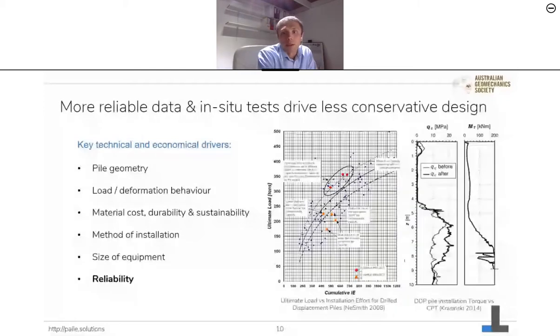Reliability is another factor to be considered, and reliability of constructed piles may vary depending on the chosen method of installation and monitoring. For example, precast-driven piles driven to set under professional supervision and with full monitoring and data analytics will provide much greater level of confidence as compared to a bored pile drilled without support and constructed by dumping concrete from the back of a mixer truck.